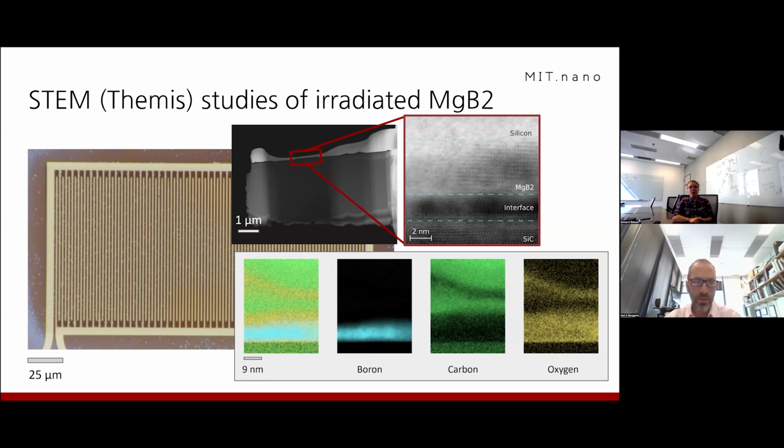Part of the advantage comes from operating it at a cool temperature. Due to the cold operating point, we're going to have fewer thermal photons that are going to confuse the noise. So to some extent, if you're really trying to minimize the dark counts, you actually don't want to operate it at a higher temperature. In operating it at a higher temperature, we would have some trade-off in the dark count rate, but we still get these other advantages like the ability to detect single photons in the near infrared and having very fast reset times.